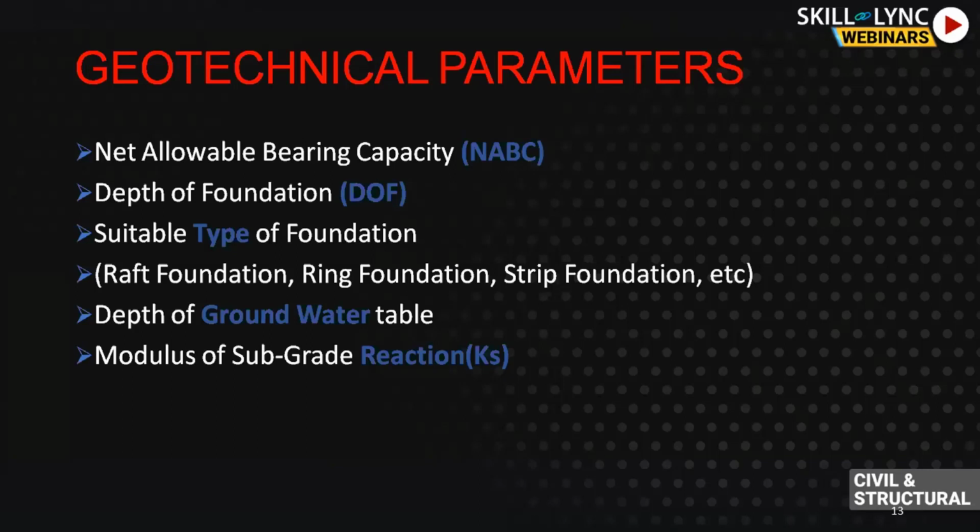This is a serviceability consideration. It's not like buildings which have many floors, good ductility, good connections, good stiffness, and more weight, where groundwater cannot do anything. But underground tanks are sometimes like cantilever structures, just joined in one direction with each other. So groundwater can uplift your entire structure. I'll tell you in the next slides also.